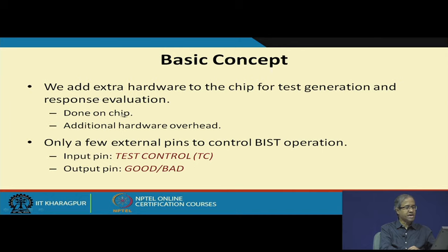So, this is the more conventional approach, but here our test generation and response evaluation both we are doing inside the chip itself. We are not relying on an external test generator to generate the test. Maybe we are using some external ATE to apply the tests. Naturally, to do this on chip, we need additional hardware.